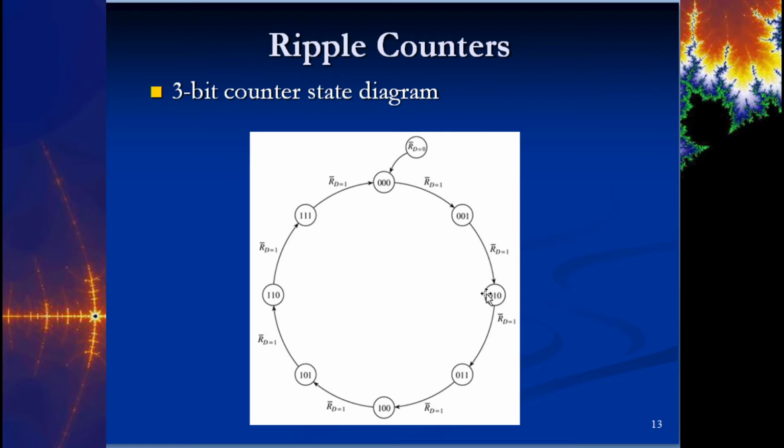And so the state diagram isn't a nice round circle where I know here's my state, here's my next state, here's my next state. The way that we did it was in terms of how much money you've put in the machine. So you could call that state 1 and state 2, but really I had state 0 cents. I had another bubble called 5 cents, another one called 10 cents. So I had 5, 10, 15, 20, 25, 30, 35, 40, 45, 50.